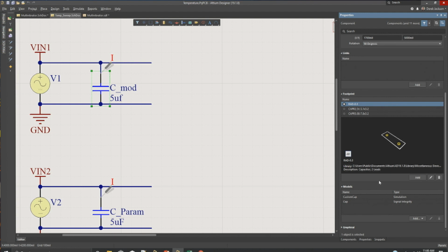If you're downloading an encrypted model, you're pretty much out of luck, because different companies have encrypted them, so we can't use them. So for each Spice model, you'll be able to support those then? Right, yeah, especially with their MOSFETs, they have a whole scheme of their own customizations. So anything that's specific to them, or if they're using encryption, we won't be able to support. So you want to look for the Spice 3.